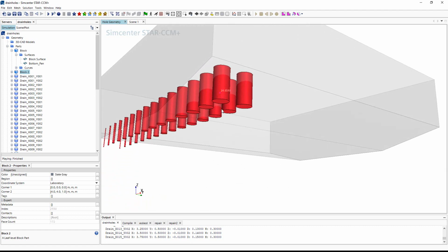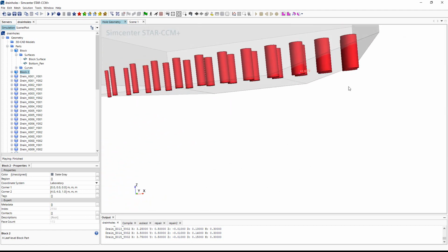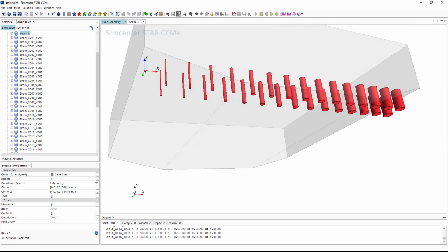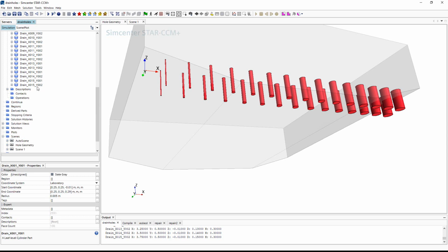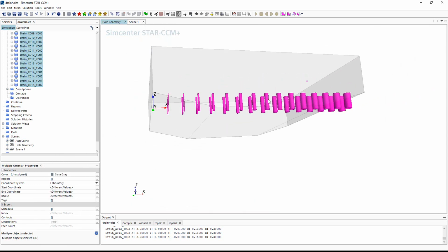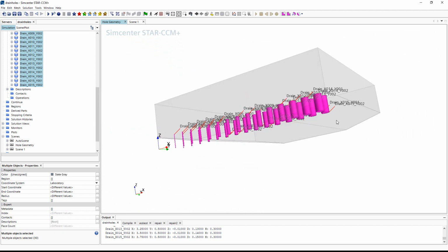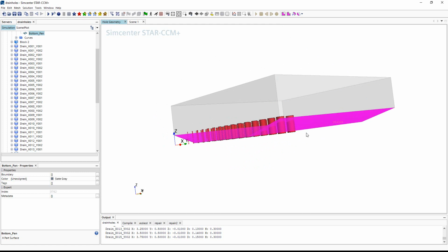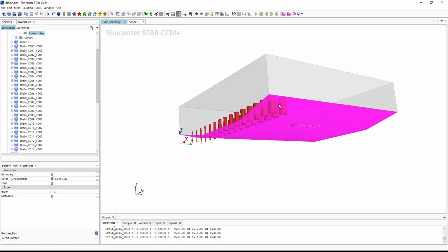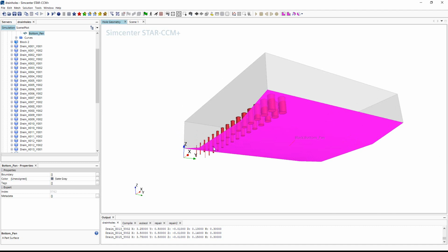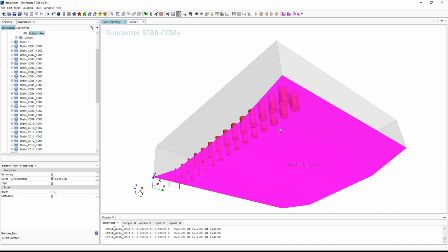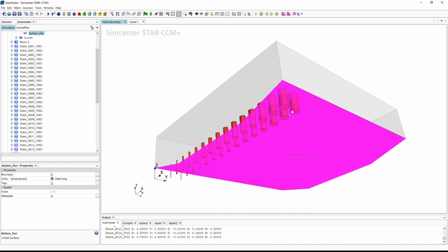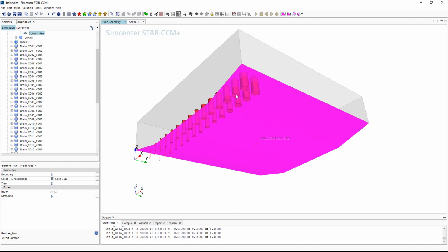and you can see my cylinders were created using the dimensions in my file. You can see each one is a separate part. It has just the default surface name. And now you can use these in surface repair to make the intersects with our bottom pan here, and then remove the excess and name the remaining circles accordingly if we had wanted them to have individual names. For example, if you want to track mass flow rate through particular holes. But we didn't do that step, and that's the intersect step in the macro.